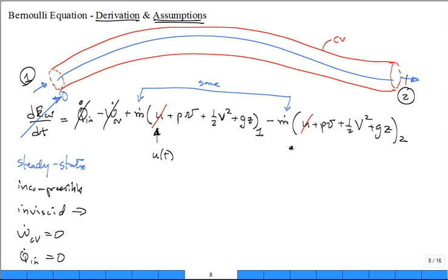I don't have any viscous dissipation to turn the mechanical energy into internal energy. Because it's inviscid, with no viscous effects and no heat transfer, the change in U is negligible. And what do we get? We get an equation that has how many assumptions? 1, 2, 3, 4, 5. There's one I forgot, 6. It's along a streamline. Don't forget that.